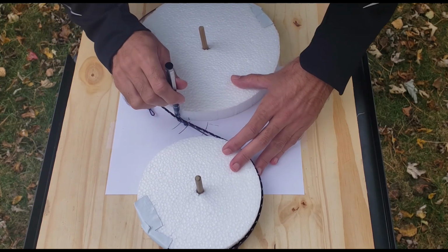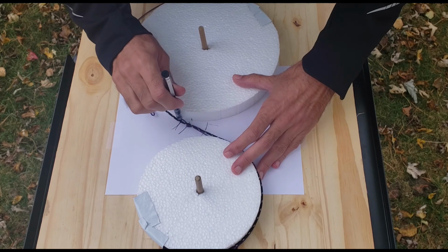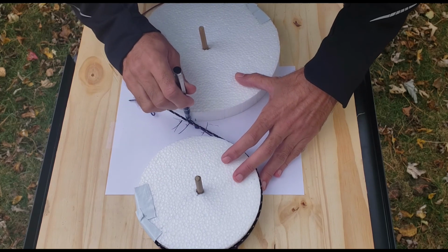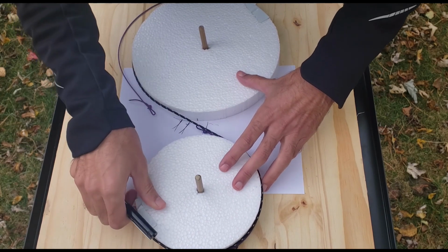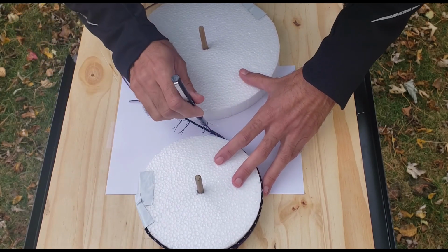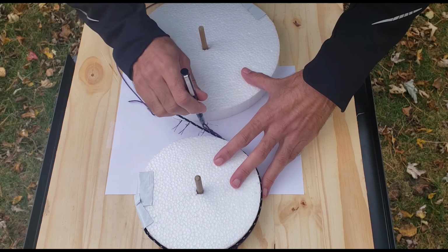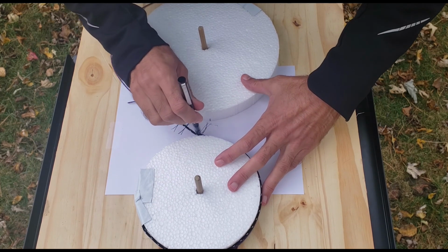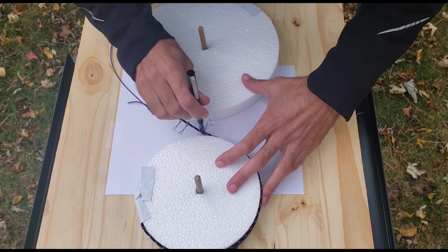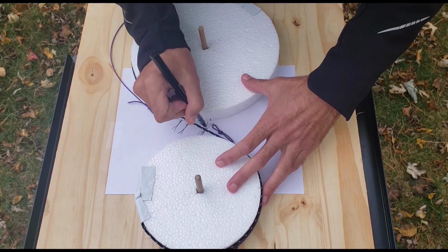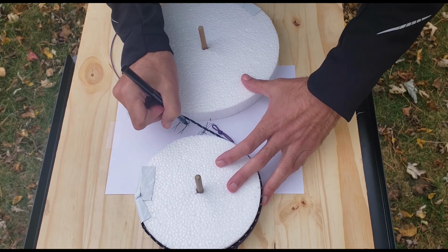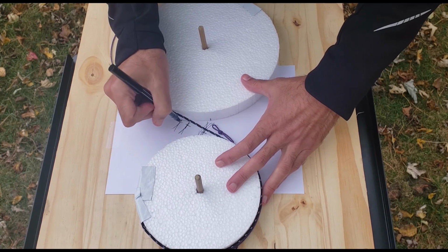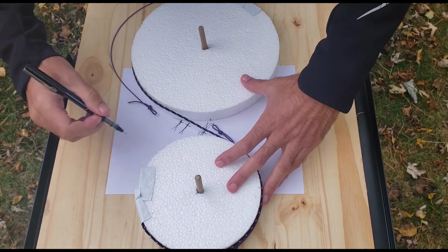Now I'm drawing tooth surfaces coming from the pinion and showing how, as I trace the surface, if I rotate the gear to the right position, if I trace a surface such that the tooth surface is right up against the mating gear tooth surface, then they cross right at the pressure line, and at the contact point, the common normals point right along the pressure line.